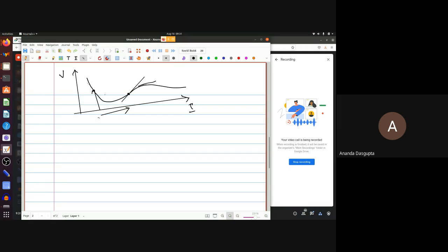Of course, you could use a Z parameter model with quiescent point here to describe things around this. Another Z parameter model with quiescent point here to define Z parameter values to explain situations here. Another one to explain situations here, and yet another one to explain situations, say, here. Entirely different looking tangents to this curve, entirely different looking Z parameter equivalent models. And that's fine. By putting together the information from each of these, you get a very good idea about what the thing is going to be like.